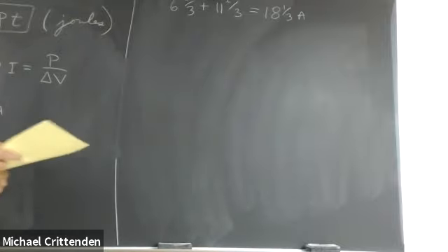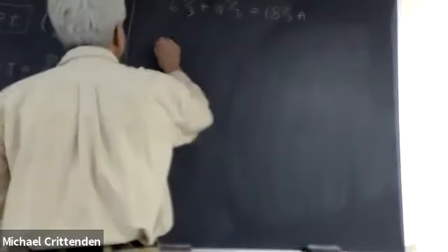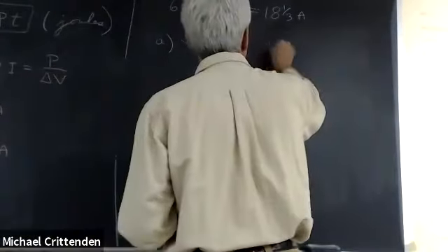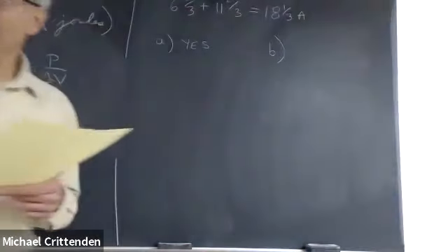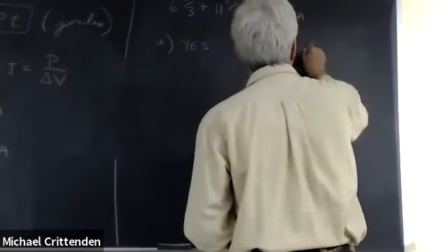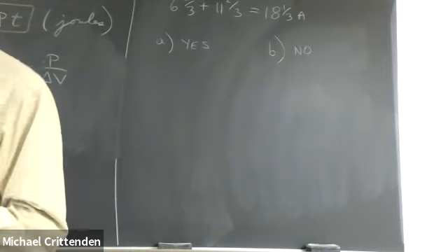So if it's a 15 amp circuit, will the breaker trip? Yes. But if it's a 20 amp circuit, will the breaker trip? No, because 18 1/3 is less than 20.